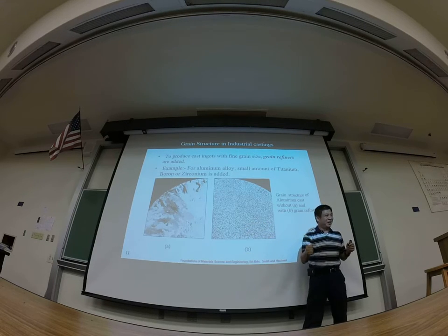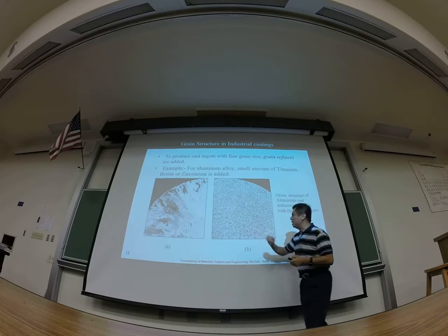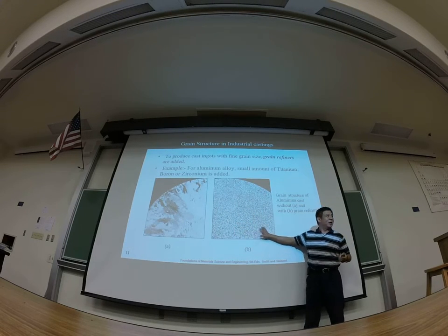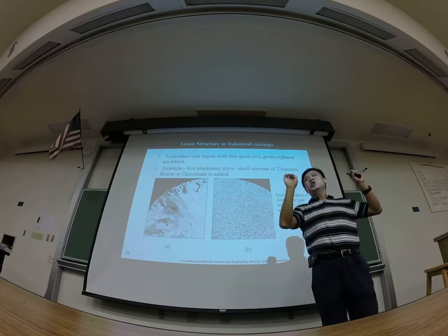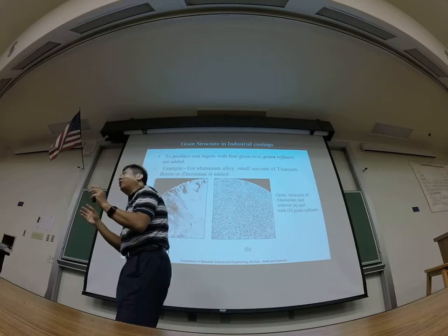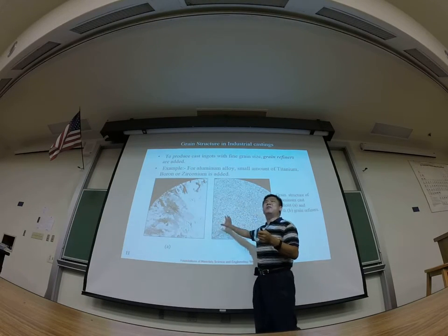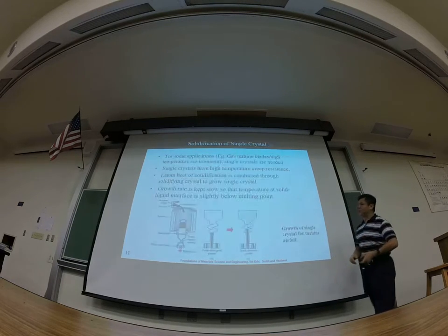They are stronger. So in chapter 6, I will explain why that happens. To generate these finer domains, what you usually do is add some seed particles, or sometimes you could even add some impurity particles inside, to induce the formation of the smaller domains.